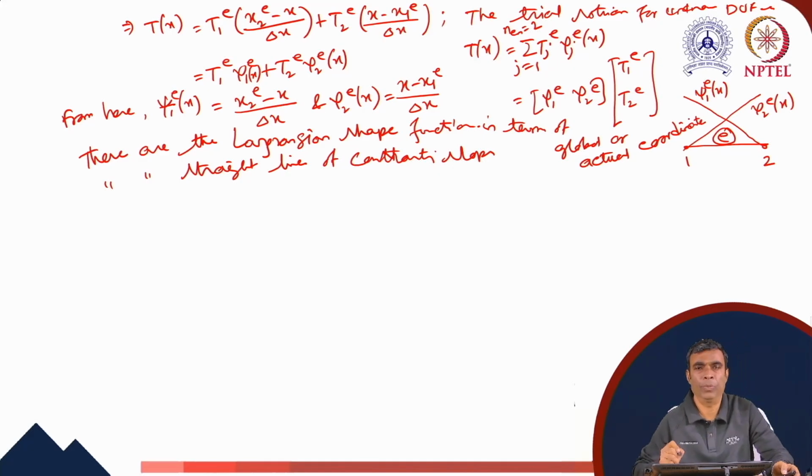Okay. So when we do FEM calculations, the shape functions are converted in terms of the local coordinate system for performing the numerical integration or the Gauss quadrature.